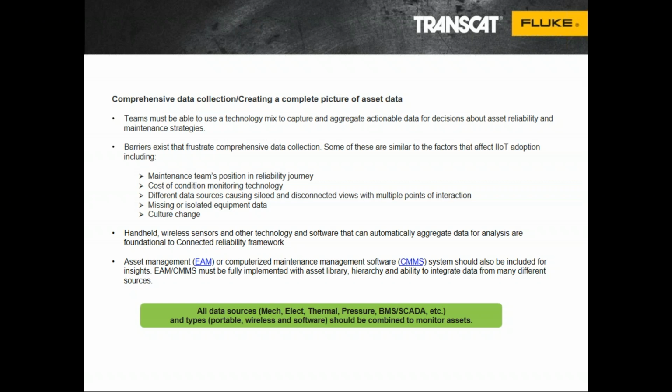If I have some thresholds or some sort of alarm strategy built into that unit, so that when I take a measurement it's telling me yellow or red, that hey, this is not acceptable, or we're in a yellow zone based on the indication I'm seeing for this particular machine type, right there, from just taking that measurement, we're getting actionable data.